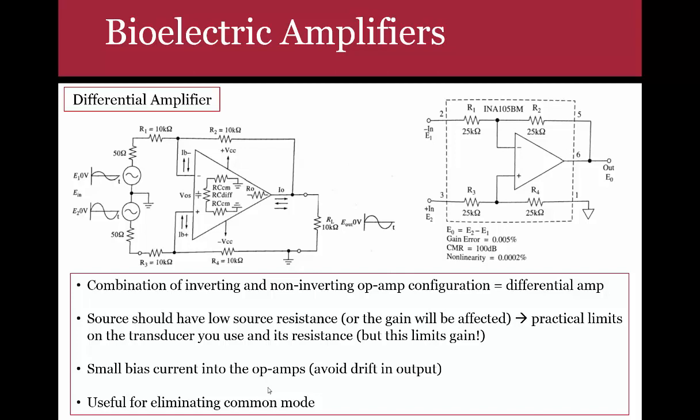I'm calling it an offset, but in practical terms, it's called common mode. The common mode is basically the DC offset noise that is sitting on top of your signal. And in this case, it has to do with the electrodes and their interface with your skin.